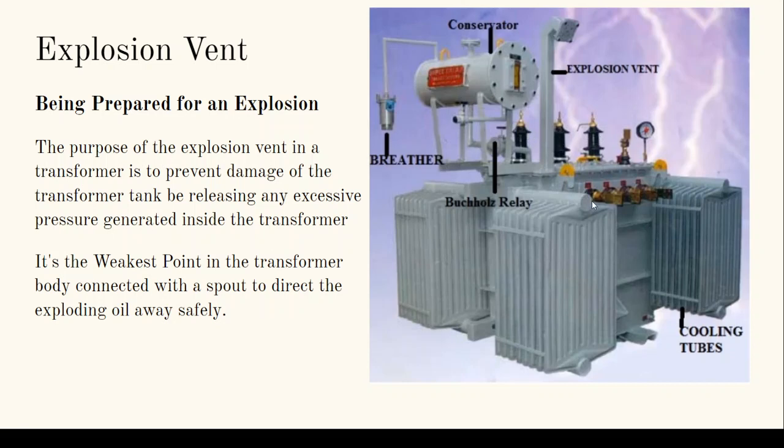So that's one thing. Next thing I want you to notice, there are 3 high voltage terminals, which is the 11 kV line, and then you have the 4 terminals here, which is your low voltage side or LV side. How come 3 to 4? This 3 means it's delta connected. When there's 3 terminals, it's a delta connected connection.